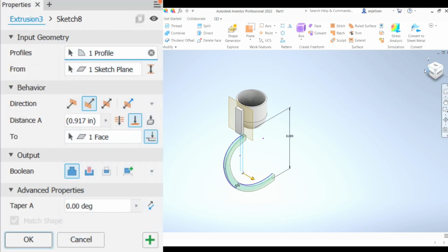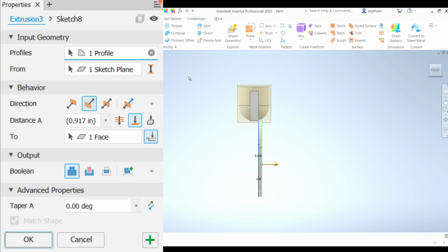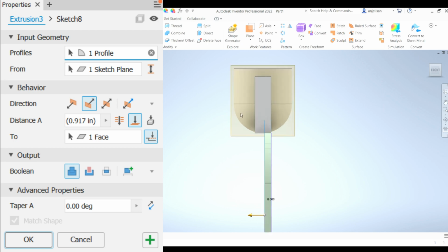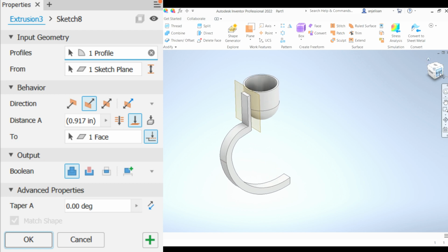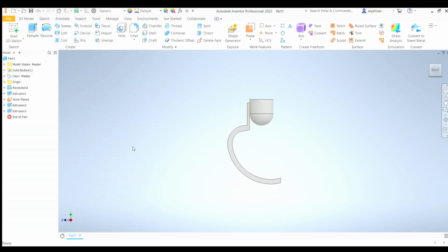So I hit the extrude function, and I make sure it's going in the right direction first of all. So I flip it, and then let's say I don't remember how wide this rectangle is, so I could just select 2 and then hit this edge of it. Automatically makes it as thick as this is wide. Okay, so now we have a rough sketch of our cheetah blade.